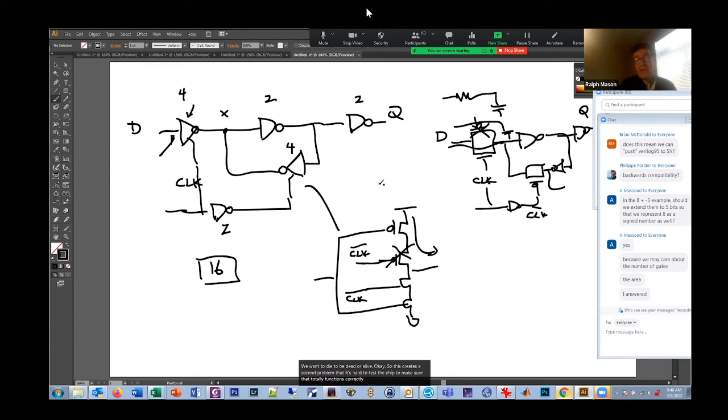And then there's a third issue: when you're laying out these transistors, these Ns and Ps that connect together like this, the layout is not very efficient. We're not going to get into layout, but trust me, in this circuit, where the Ps and Ns are connected on both sides, here I only have them connected on one side or the other side. This turns out to be a much more efficient layout, so I can make it more compact. So even though it has more transistors, the layout is more compact, so it takes a similar amount of size.